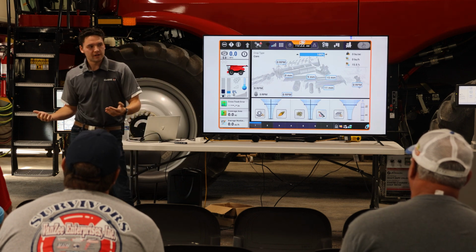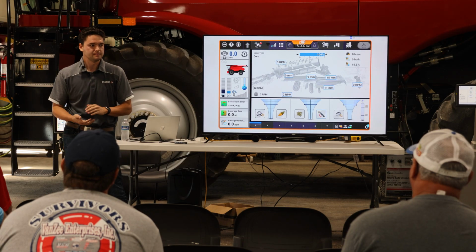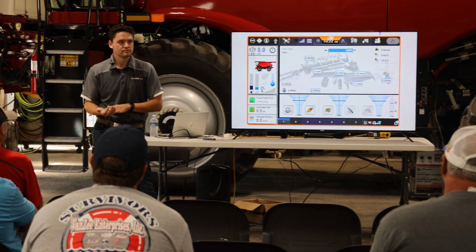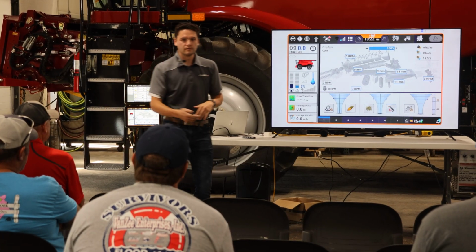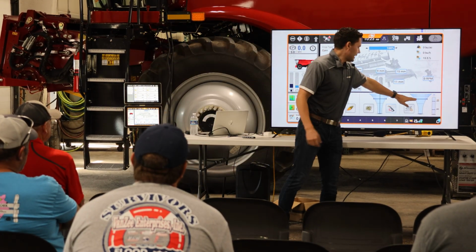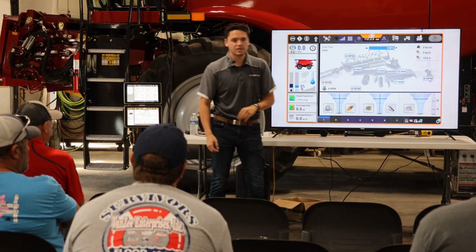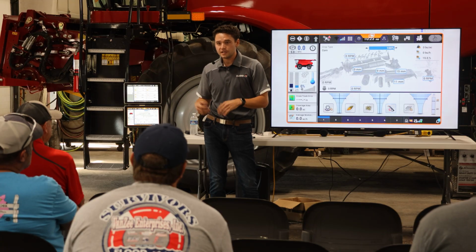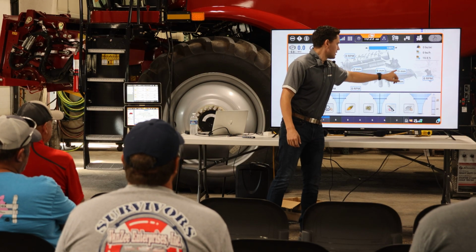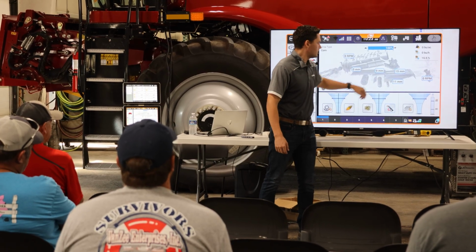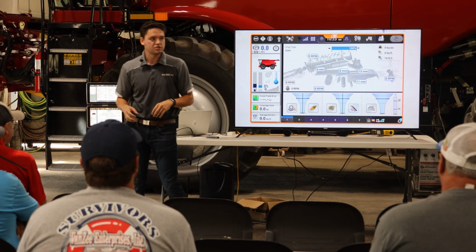So in normal operation, when we experience that, what should we really be doing? What should be the operational practice there? Rather than making the change ourselves, we should keep going for a while, let this rise above the trigger point, and make sure automation is the one that's making a change. If you want to know, is it actually making a change, and what did it make a change to? In this scenario, if it's sieve loss, you'll see the upper sieve, or maybe our cleaning fan, highlight blue, and that'll be the indicator of what it's making a change to.